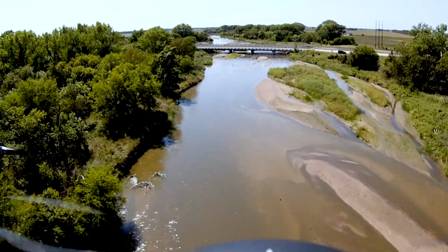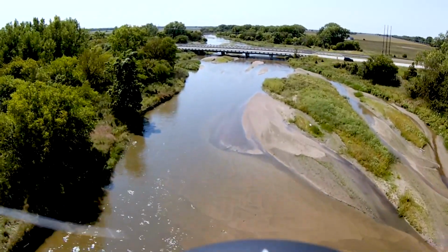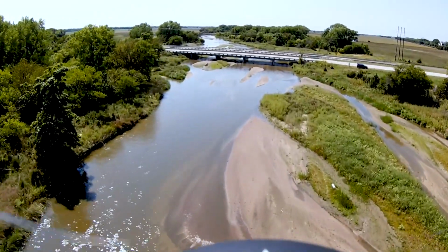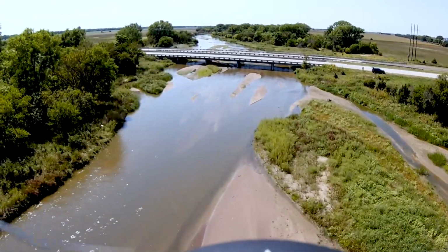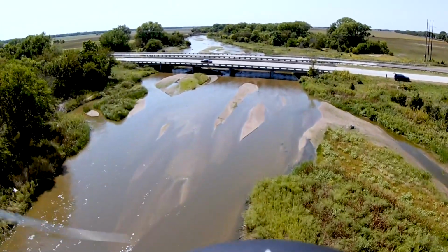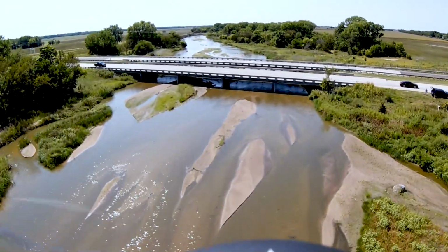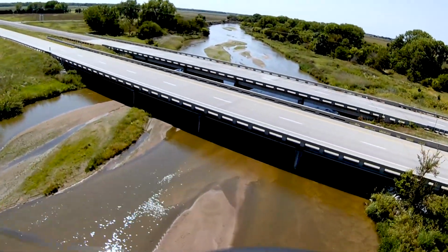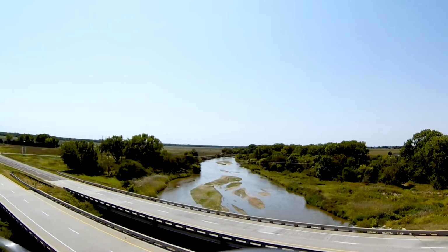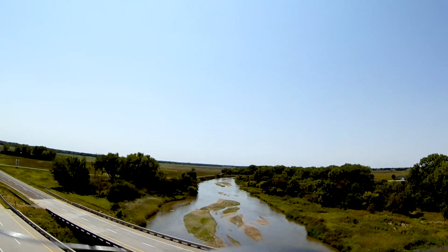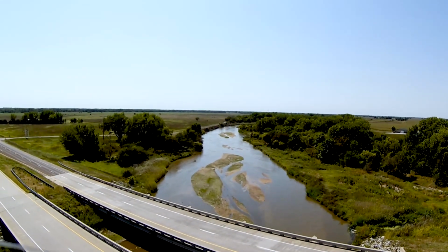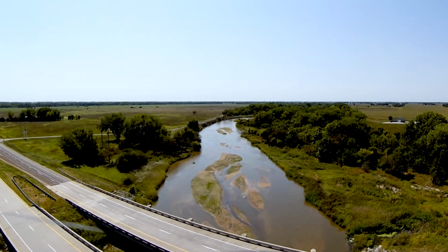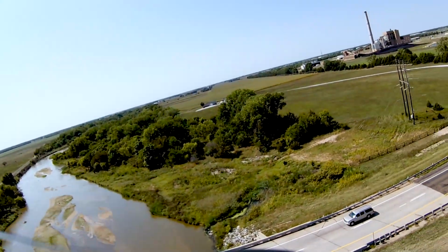Those little jerks in the camera that you see at different points along the flight happen when it reaches one of its waypoints and makes a slight turn. Unfortunately, the camera I'm using on board doesn't have a gimbal or anything to keep it steady, so any movement is very noticeable. I'm going to try to find the settings for the yaw axis and see if I can tune out those abrupt changes, maybe make the video a little more stable.